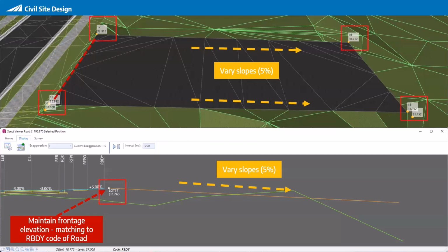One thing I just want to highlight to you, and you've maybe seen these red boxes appear, is that we can show the Cogo points in a couple of different environments. At the moment, we can see them in the cross-section window, and we can turn those on with this survey tab, which came in V23. And I can't remember if it was in V23 or possibly V22.2, due to the fact that we were adding in, obviously, the survey points and the survey lines, etc. I think it was V23. Or no, sorry, V22.2. We added the option to add the Cogo points into Model Viewer as well. So they're actually at their elevation with a little display marker, which, for context, can be very, very helpful.